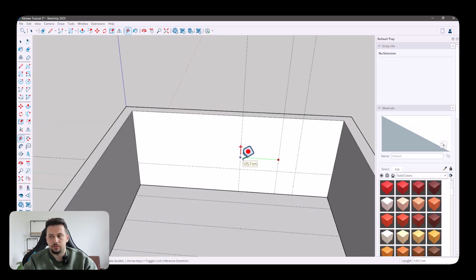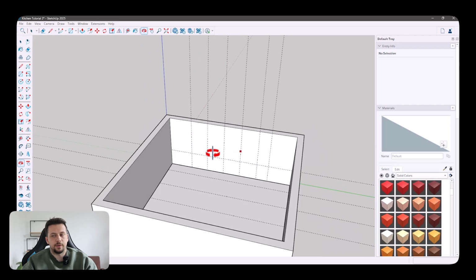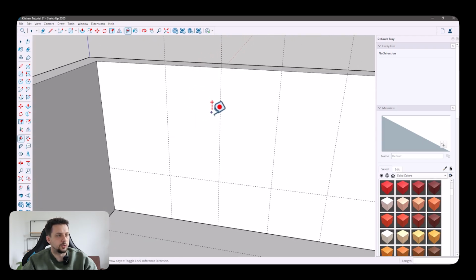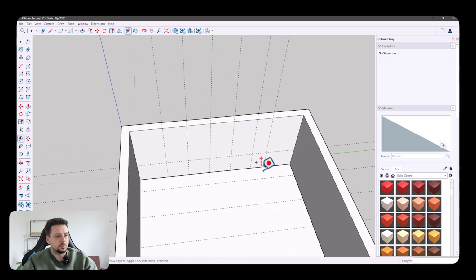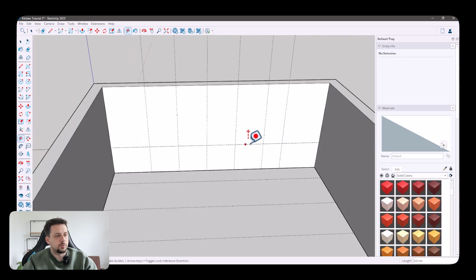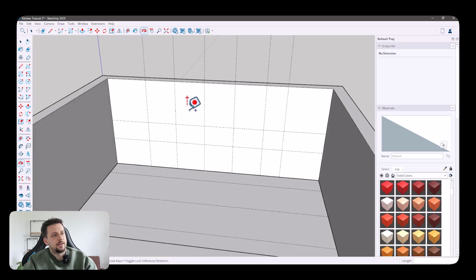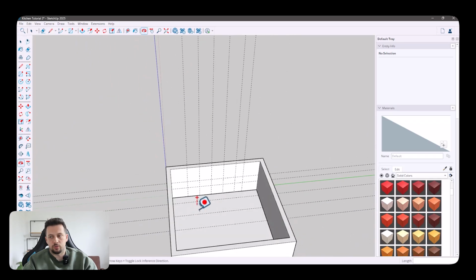And then we'll have one base cabinet here, another one over here, another one over here. But I think this one should be the final one, which is a tall cabinet which can serve, or we can have a pantry here. And we'll see how that will play out. Then in terms of the distance from the base cabinets to the upper cabinets, we will do about 60 centimeters. And now we have things a bit more organized for us.